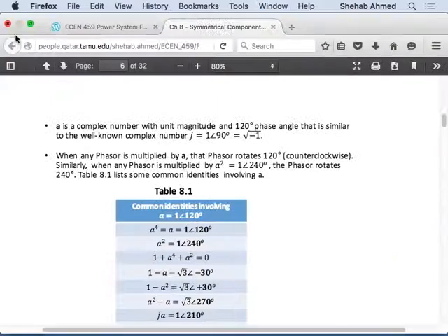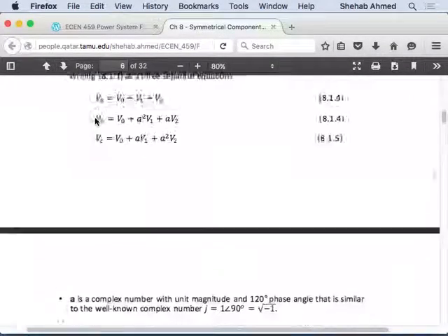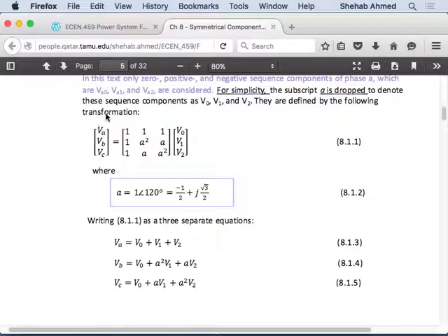So if I am measuring my phase quantities and I calculate my sequence quantities, my phase quantities will give some measurement. These measurements will be unbalanced, right? If they give unbalanced measurements, and you then calculate your sequence quantities, you find a value for V0, V1, and V2. What will that mean? It means that the system is unbalanced.